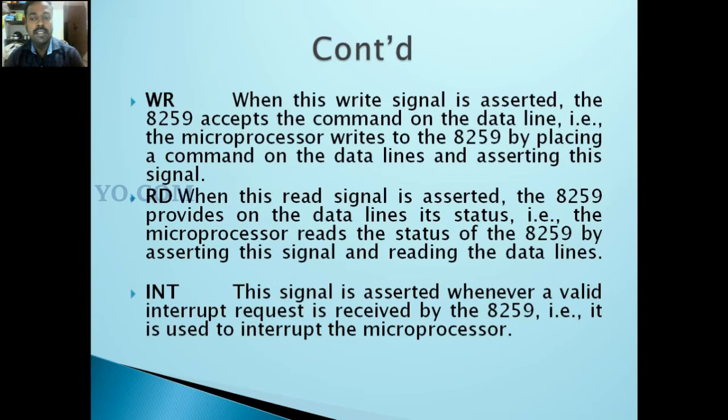The address of each ISR for each interrupt device is fixed. As per the requirement, these addresses are spaced 4 to 8 bytes apart. Any portion of the memory may be used for this. The 8259 can be initialized with 4 ICWs. The first two are essential and the remaining two are optional depending on the modes used.